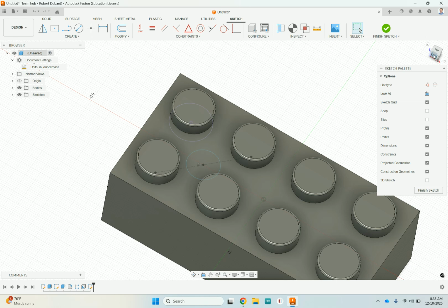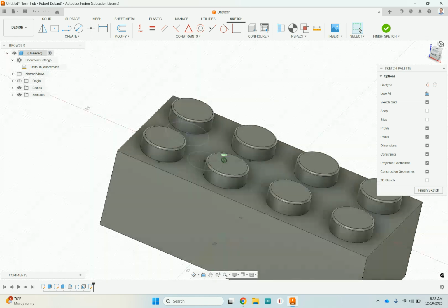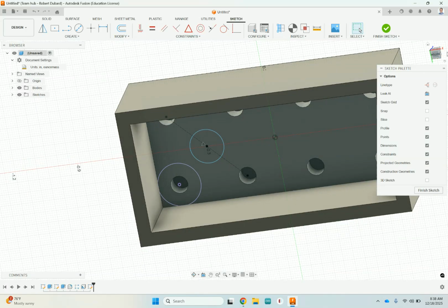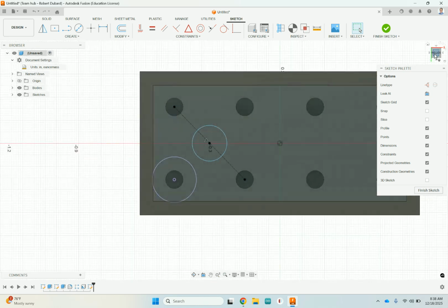What I'm going to do next is try to get back to the view directly on my sketch. I'm going to click up here in the view cube and roll it back over like this. And then look at the view cube. I see it's bottom that I want to look at. So if I move my cursor until it hits the center of that word, bottom, up here in the top right, you see where my cursor is, I'm going to click that. And that's going to make me straight on again with my sketch, so I feel more comfortable that my sketch is making sense.